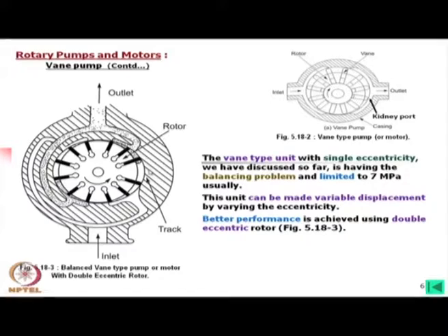And this is completely circular one, and while it is rotating, it will have two suction and two delivery sides. So, you can see these are connected, this is suction and this is delivery. For each 90-degree quarter, there are ports. These are also kidney type ports, but special ports. This is definitely expensive.